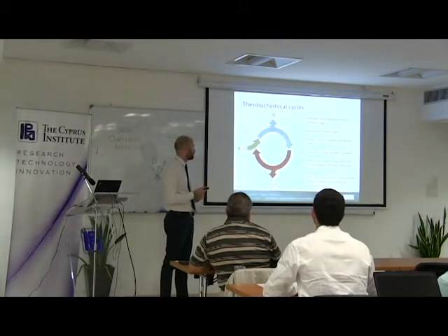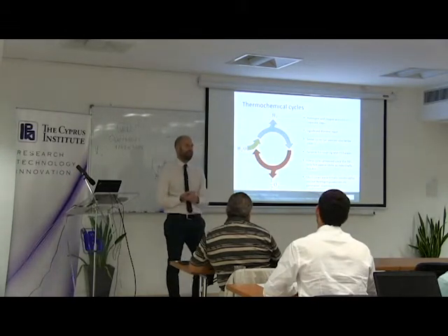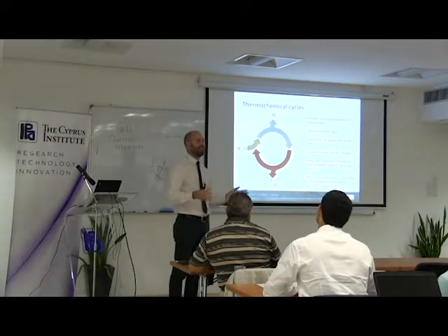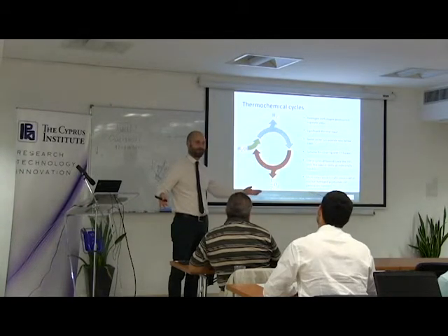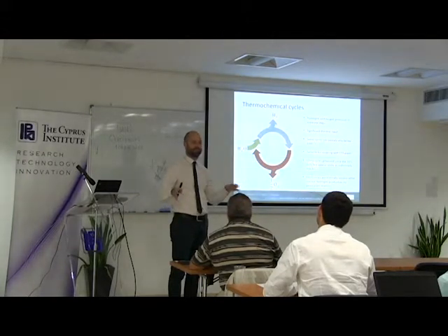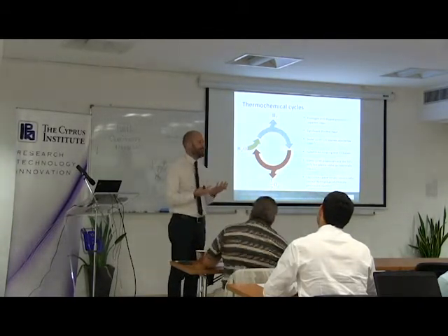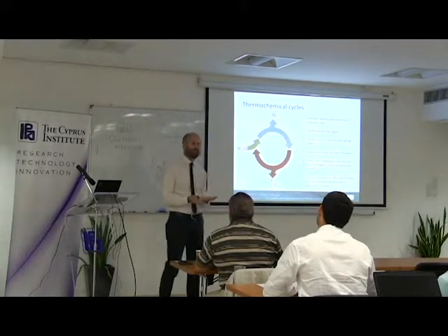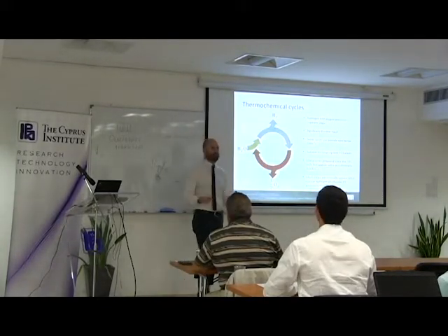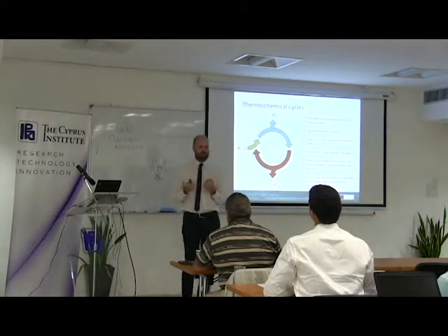You may know that the fourth generation of nuclear reactors, the so-called very high temperature reactor, is a type of reactor that has a big amount of rejected heat, just like the power plant we talked about. The difference is that the rejected heat from the conventional power plant is at 40 Celsius degrees. The rejected heat from fourth generation reactors is 1000 Celsius degrees. So it's not really a waste. It's a very, very valuable source of energy. So it was thought, let's use this high temperature heat to produce hydrogen. So all these processes were conceived to use this energy input.